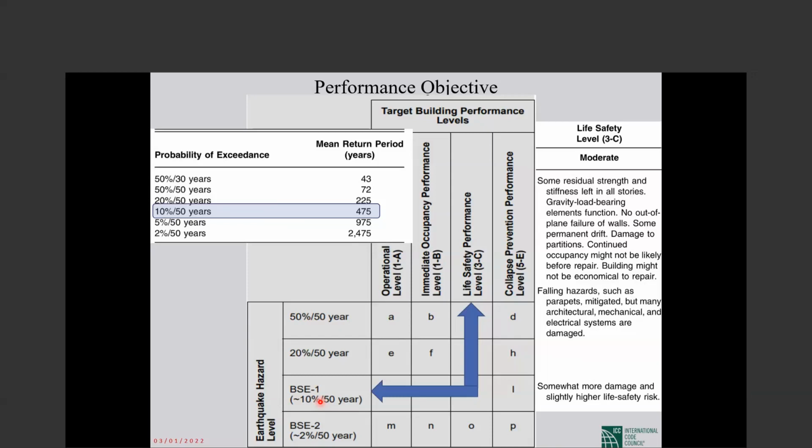There is no R factor in the existing building, because the real R factor for an existing building will be very small. So we forget about R. For every element, we find its m factor.